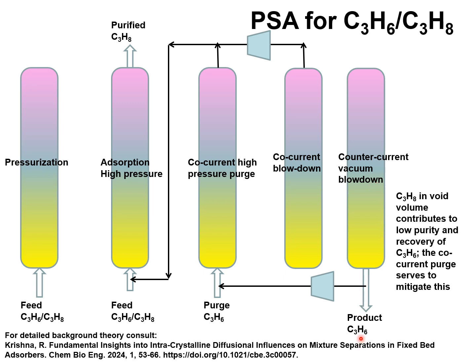In order to achieve high purities of the desired propene product, it is important to have adsorbents that practically exclude propane from the pores, because any propane left in this final blowdown stage will contribute to low purity of and recovery of the desired propene product.